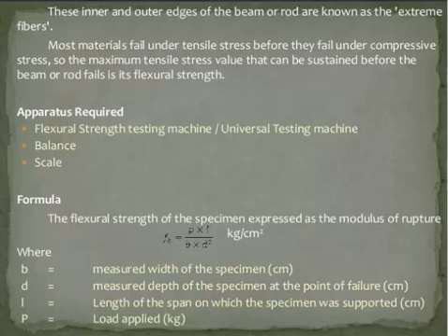The flexural test on the concrete can be conducted using either the 3-point load test, ASTM C78, that is the code referring to the 3-point load test for the flexural test, or the center point load test, ASTM C293, the code referring to the central point load test for the flexural strength test. The configuration of these loading conditions I'll explain later.